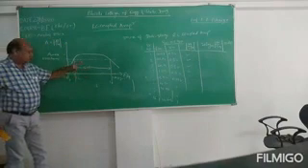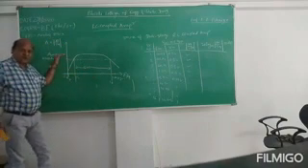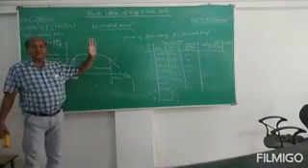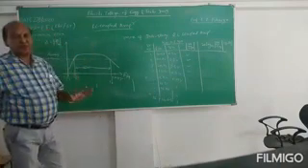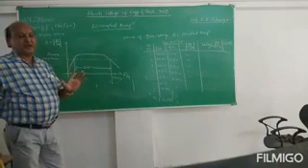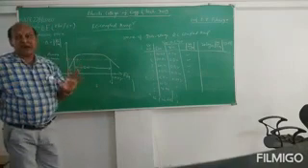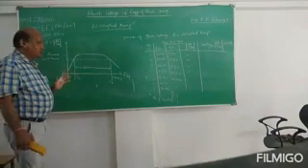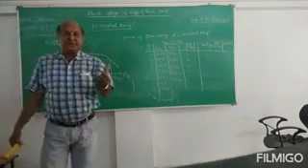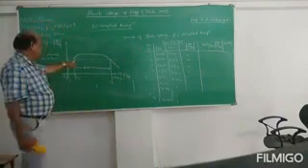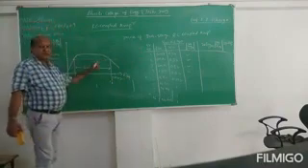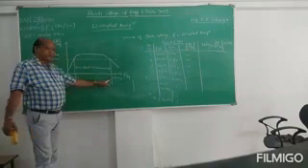That means within this particular bandwidth, we will get a flat response of the RC coupled amplifier that we have to show. What is the purpose of the practical? To verify the bandwidth of the RC coupled amplifier, to see whether in a particular bandwidth we will get the flat response or not. This flat response we will obtain by plotting within these two frequencies.